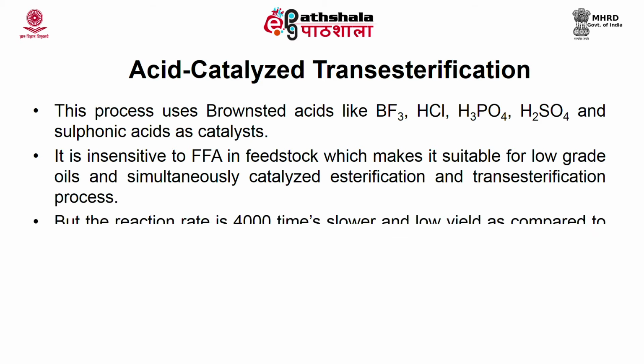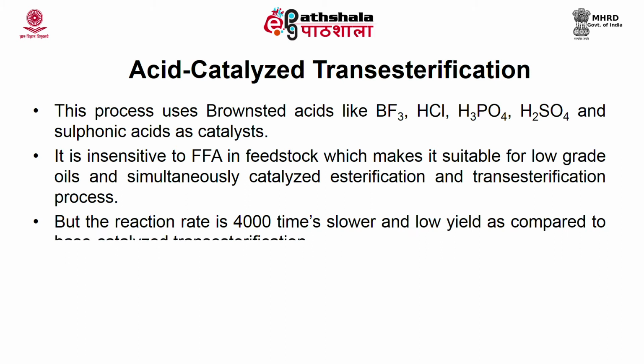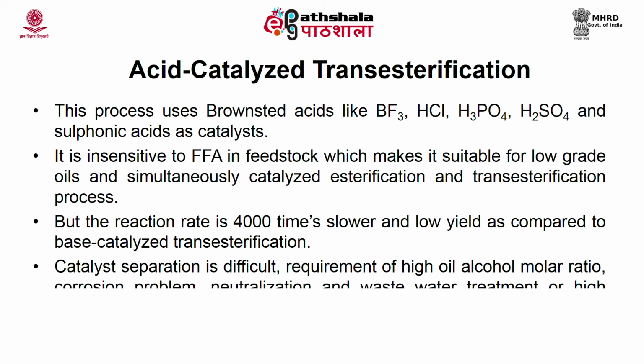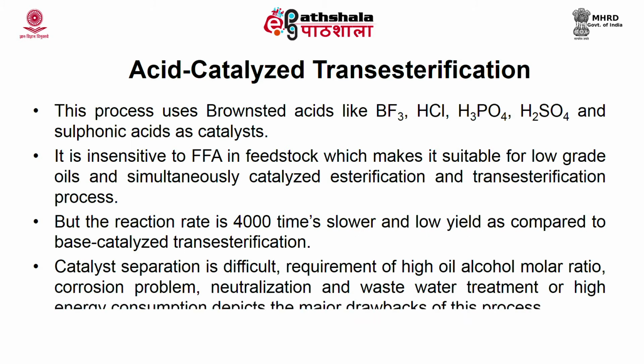But the demerit is that the reaction rate is 4000 times slower, with low yield in comparison to the base catalyzed transesterification. Also, the catalyst separation is difficult. There is a requirement of a high oil to alcohol molar ratio. There is a corrosion problem, and neutralization, wastewater treatment and high energy consumption are some of the other drawbacks of this